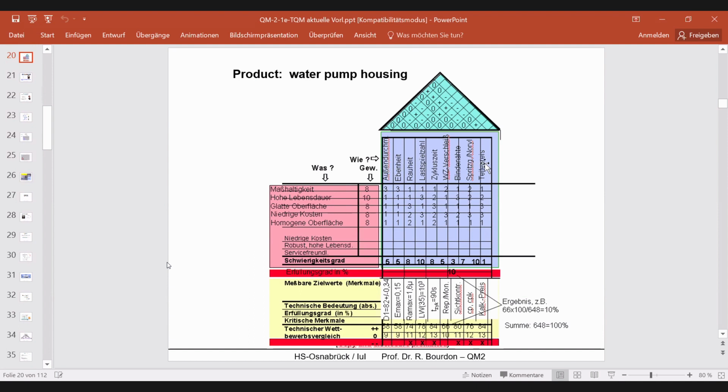Here you see the quality characteristics. It is important: outer diameter, flatness, the roughness. Here it is the cycle time, the number of cycles if the part is stressed by a dynamic process, so pressure goes up and down, and then the question is what is the number of cycles, up and down cycles, which the part is doing before getting a crack or something like this. Then here weld lines and the material and of course the price of the part.